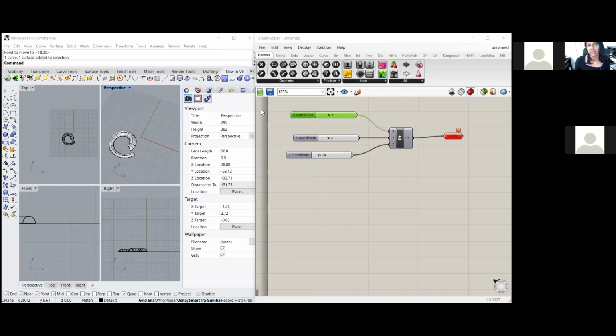There are two reasons for that. One is your point is hidden. Guys, in general, when you have a component that is in gray color, it means preview is off. Just select the component and click on the center scroll button of your mouse.